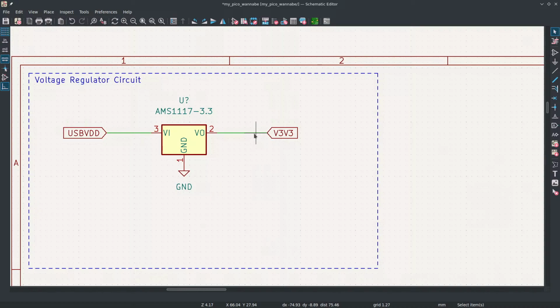So they're not very efficient. If you had 10 volts and you needed 5 volts, it's going to throw away half the power and just burn it off as heat. So it's doing a voltage division. It uses transistors and so on inside of it, but ultimately they act like resistors that vary as needed to ensure that the right amount of voltage ends up being dropped across it.